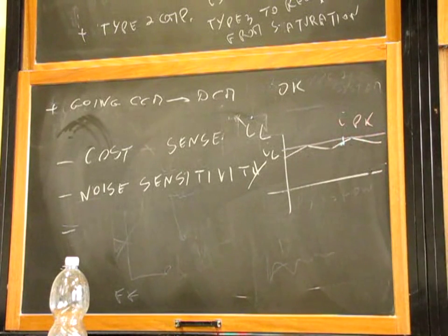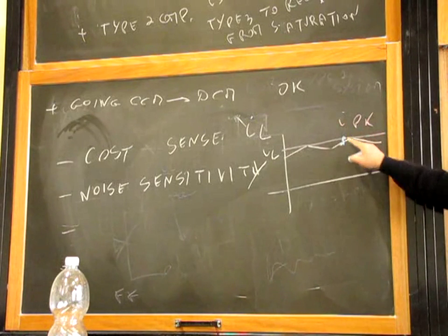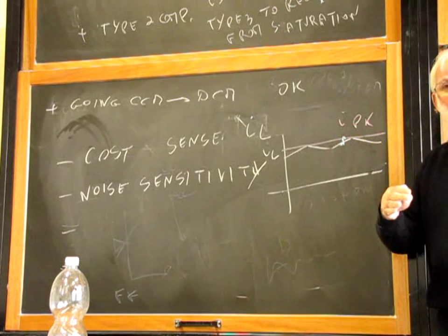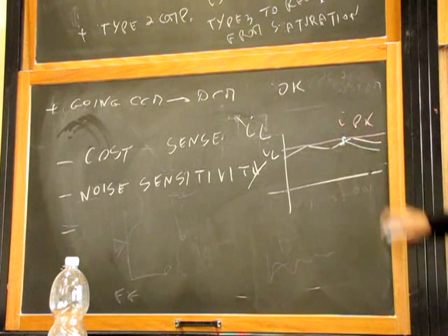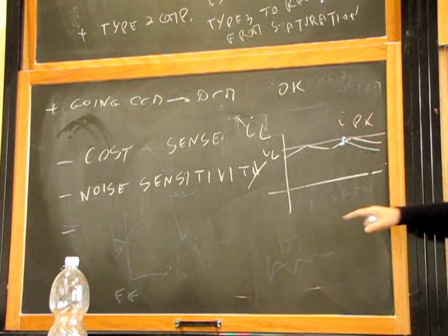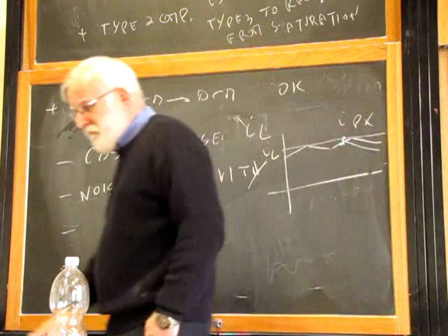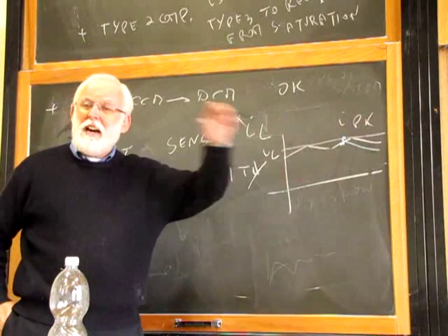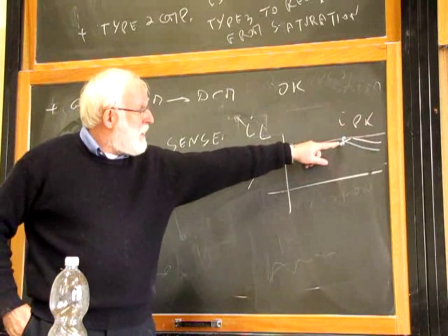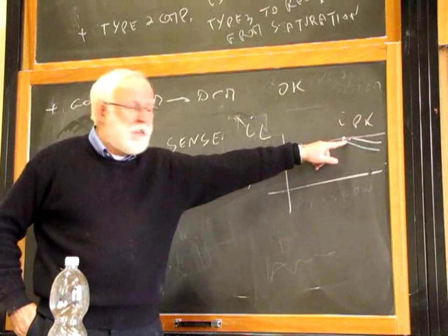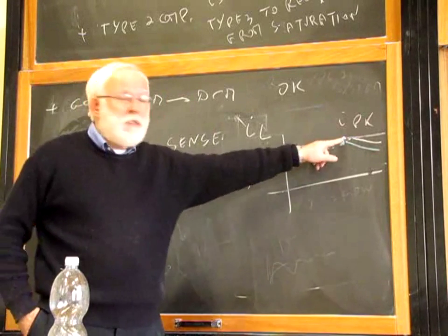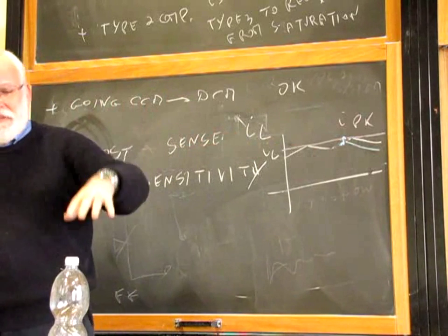It's because, for example, there is some noise coupled to the comparator. As soon as it jumps up, immediately the comparator senses, oh, overcurrent, switch it off, and immediately it switches the switch off. So current mode is noise sensitive because these 2 voltages, the peak voltage, the control voltage, and Rx times IL are very close, are always very close. And so if there is here, during this period of time, a small noise disturbance entering into the comparator, your comparator commands and opens the switch immediately.